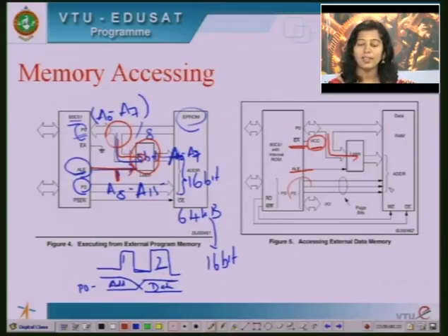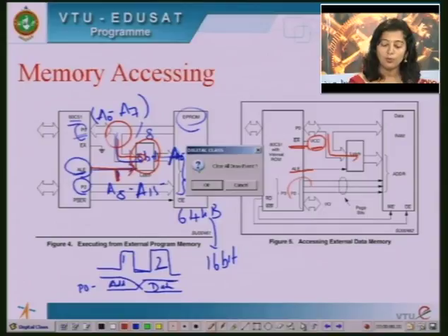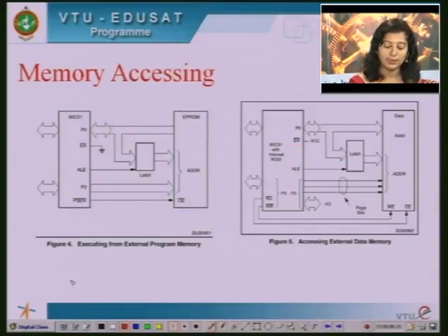So, how many bits of address do I need? That many bits I am going to use. The read and write bars of the 8051 are connected to the read enable and write enable pins. So, this is how we do the memory accessing.